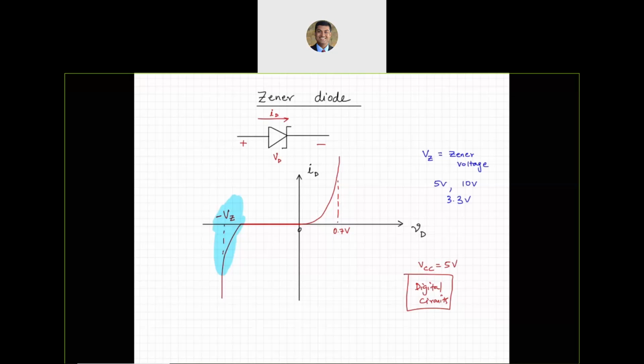So when you have ICs that are maybe expensive, maybe cheap, however, they are crucial to your design, you do not want to damage those ICs by applying a power supply that is non-regulated, which means that it can change in value. It can quickly change from 4 to 5, 5 to 6, maybe 5.2, goes back down to 4.8. So you do not want that to fluctuate.